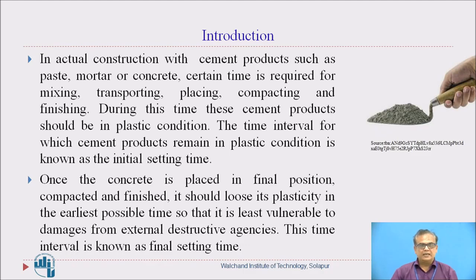So during this time, these cement products should remain in plastic condition, and this time interval for which cement products remain in plastic condition is known as initial setting time, so that working of this particular paste or mortar or concrete is possible.